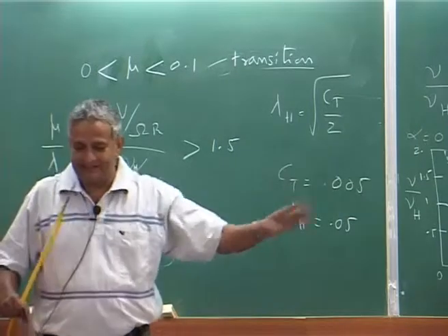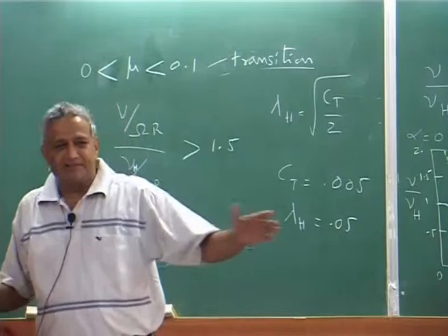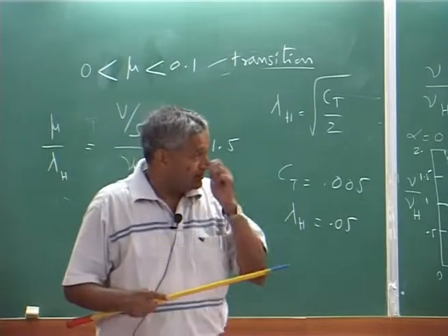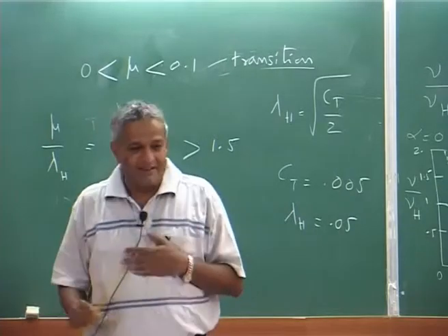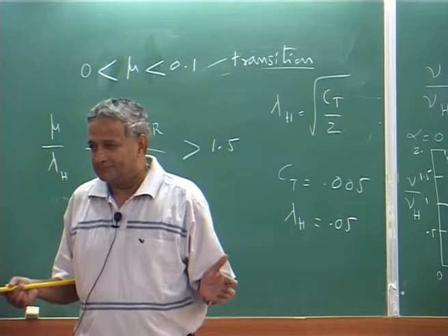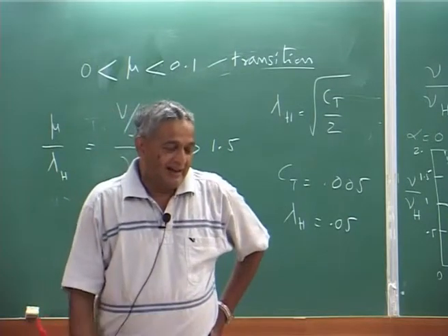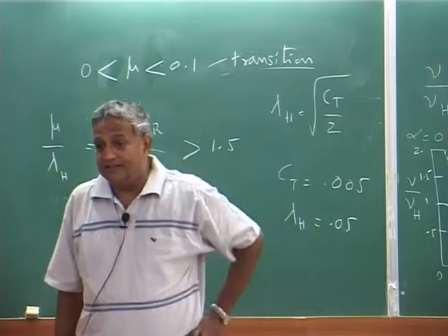So you find that in this zone, 0 to 60, you have a lot of variation in the vibration, but the important thing is the rotor behaves like a circular wing, and I said aspect ratio is very small, and as a result there is a lot of variation in the inflow.